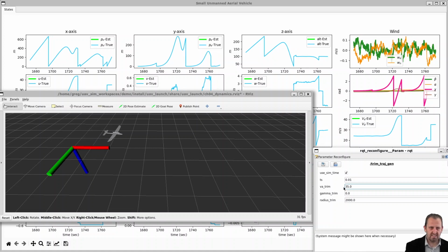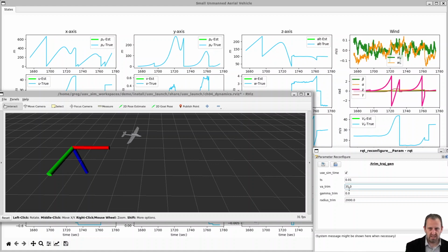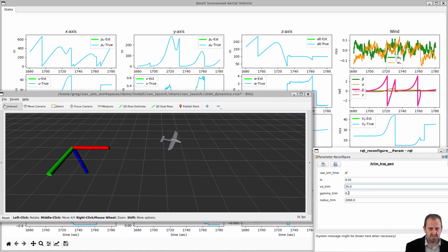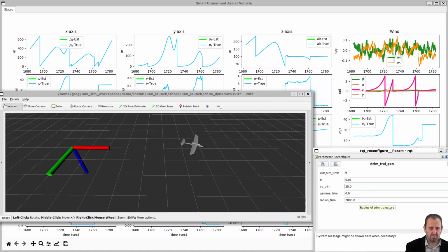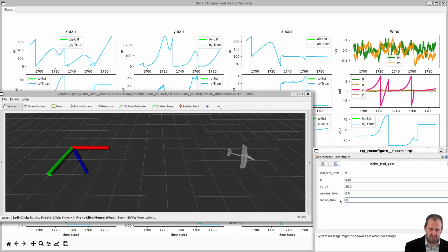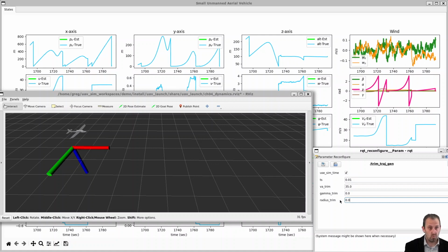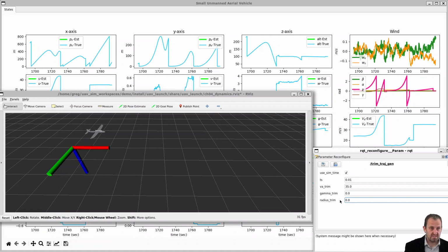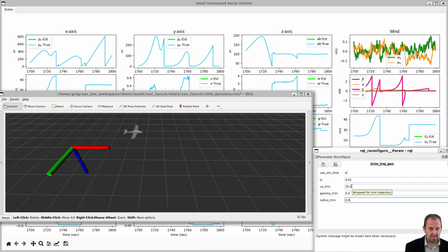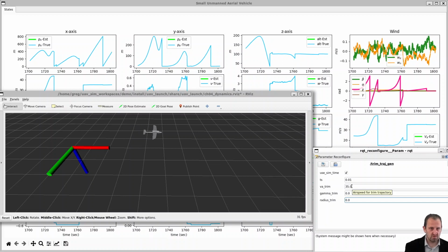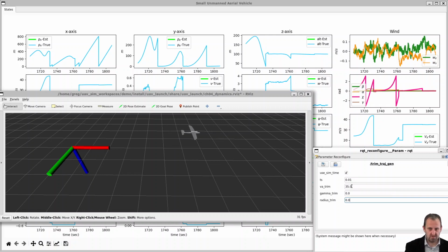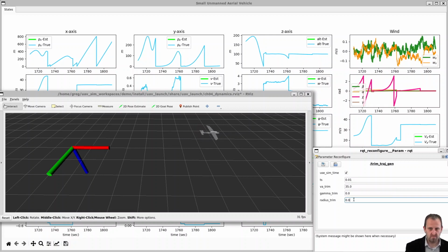We can define these desired trajectories using these three parameters, and we'll get the nominal state and nominal inputs out of the optimizer. So really cool. One other thing to note is that we can execute the straight trim trajectory a lot longer than we can with anything with a non-zero gamma or a non-zero radius.